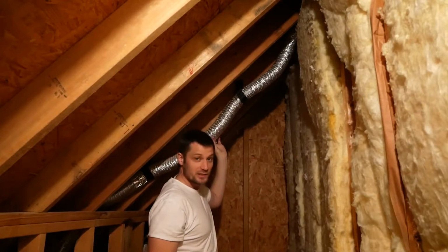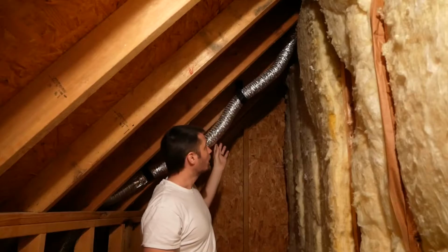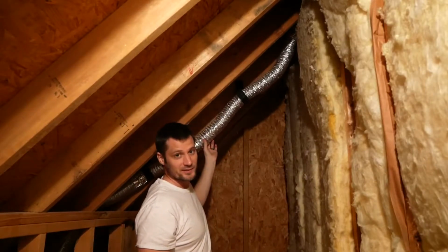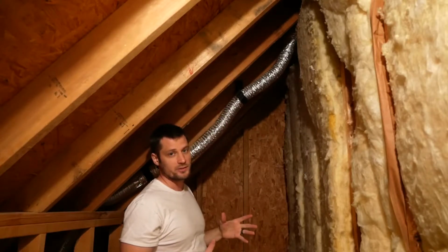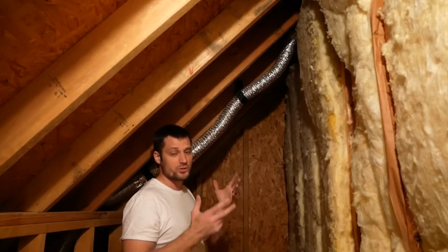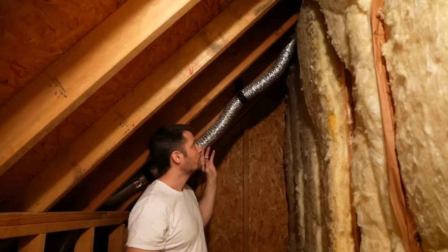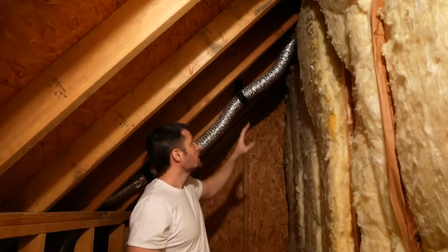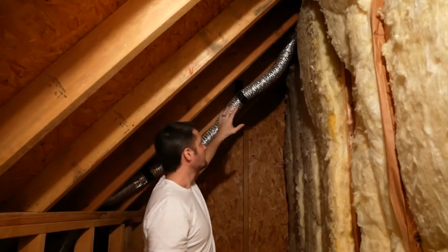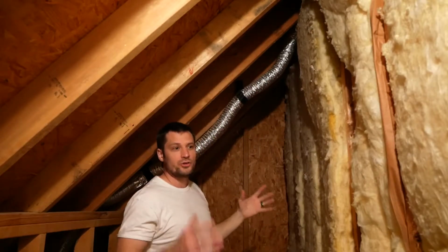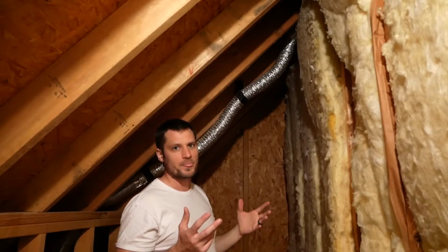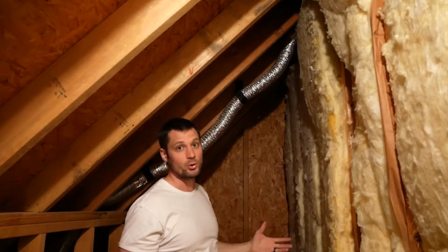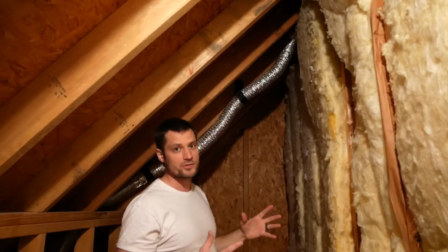And what we can see right here is the actual duct. Now, the first thing we see about this duct is it's not insulated. So we definitely want to replace this with an insulated duct. There's a couple reasons you want an insulated duct. One, we have this temperature issue that we're trying to deal with, so that should help slightly. But two, if you have air going from a conditioned space into this unconditioned space, you're going to have differences in temperature and differences in humidity as well, so you can have condensation accumulate on the inside here, which can lead to mold. So that's going to be a problem as well. So there's a couple reasons we're going to want to replace this.